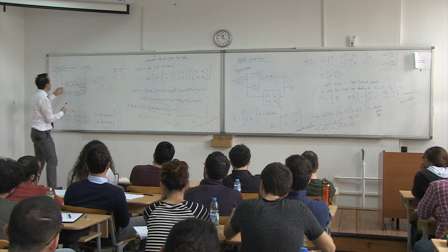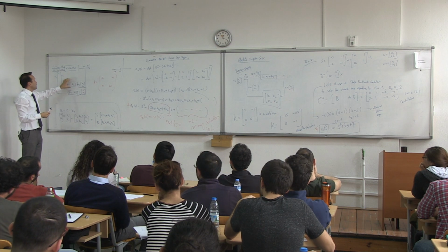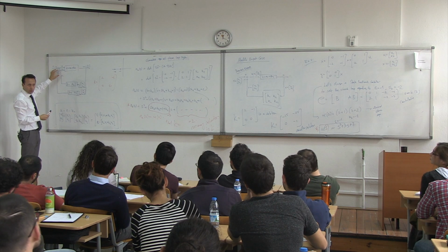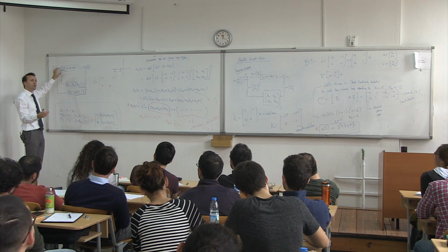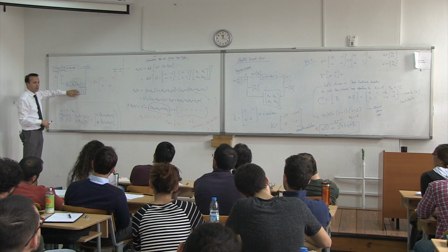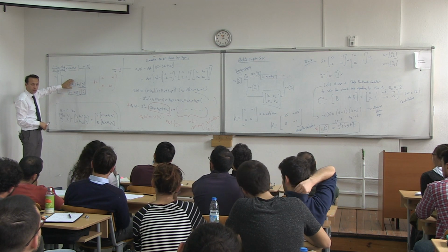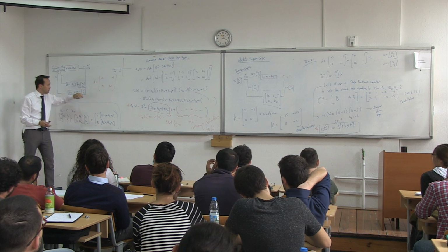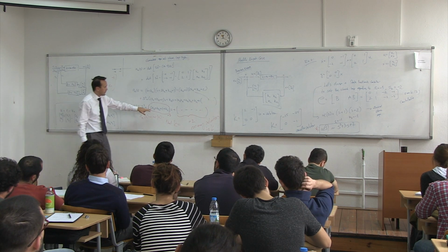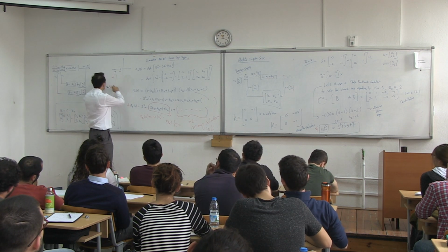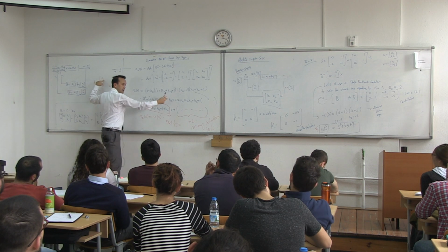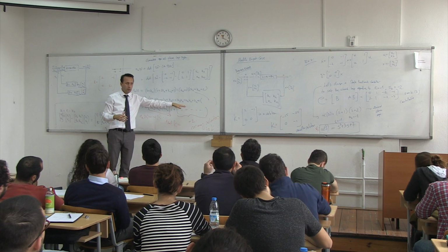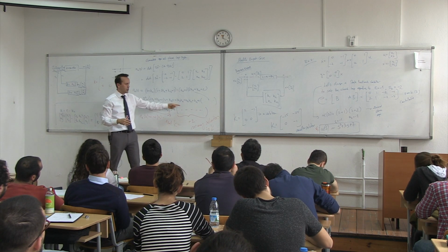If I want to move the controls over here, part of it can go to control number 1, part of it can go to control number 2. If you want to move everything to the first control, you put this equal to 0, and you can only use this. I'm sure you can find a solution where these two are 0, and you have other numbers over here. Basically, K11 and K12, set it equal to 0, and find the other two. You have two equations.